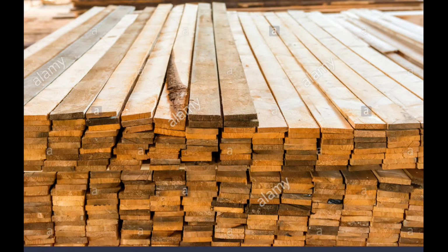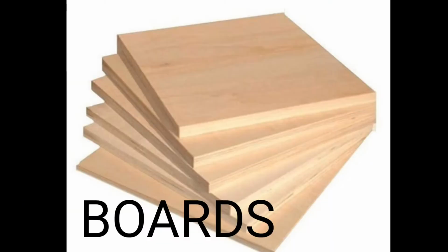2. Plank. These are pieces of wood that measure 38 mm to 100 mm thick and 150 mm or over wide. 3. Boards. These are pieces of timber that measure 10 mm to 38 mm thick and 75 mm and over wide. 4. Battens. These are pieces of timber that measure 19 mm to 38 mm thick and from 25 mm to 75 mm wide.